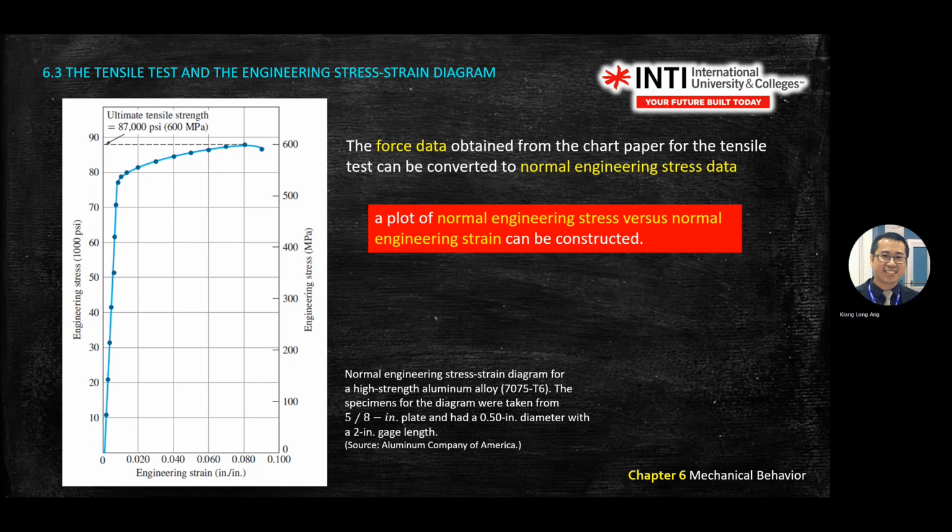Then the other one, this one is the plastic one. You need very careful measurement. Sorry, break is this point. But if you deal with a metal, it breaks very fast. Breaking very fast makes it very hard to find all these points unless you have a very precise machine like the one I showed you just now. So when you get a straight line, you can get y equals mx plus c. What is your y? Your slope is E, or Young's modulus.